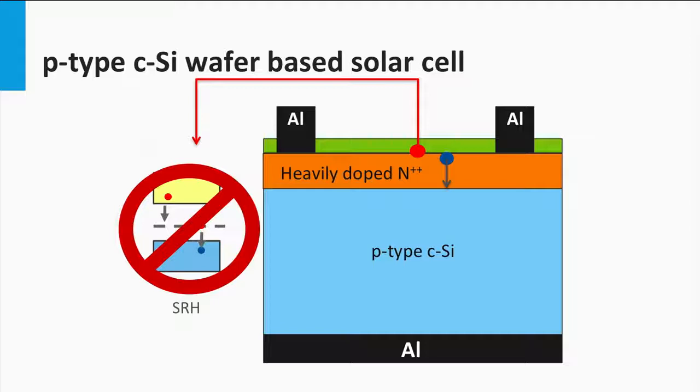However, this is again in competition with the diffusion length of the minority charge carriers. In this case, the hole is indicated by the blue dot. Note that many charge carriers are generated by the bluish photons close to the surface. To utilize these light-excited minority charge carriers, the diffusion length of the holes has to be large enough to reach the depletion zone at the p-n junction, as indicated by the blue arrow.